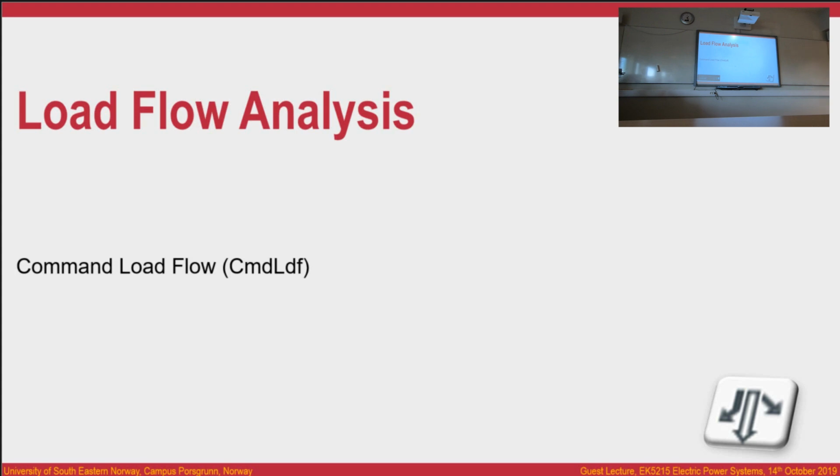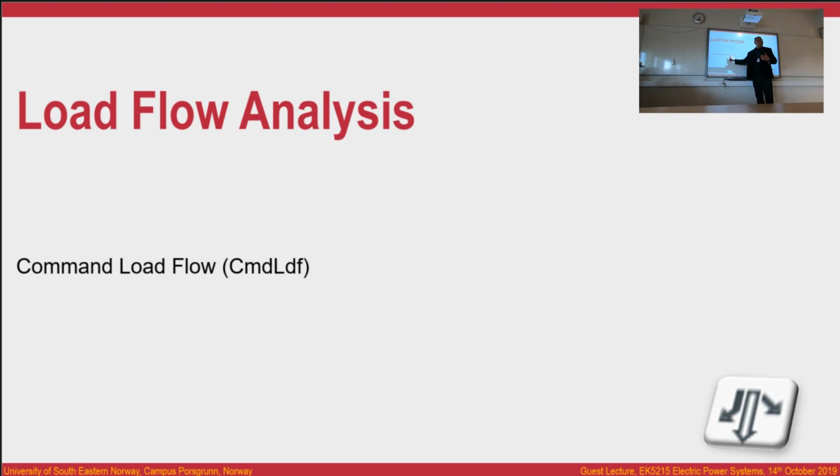The red color was the type, TYPSYM. That is the type synchronous machine. And I say that is another object. That object contains data. Are you with me? At the very beginning, I said every single thing inside PowerFactory is an object.